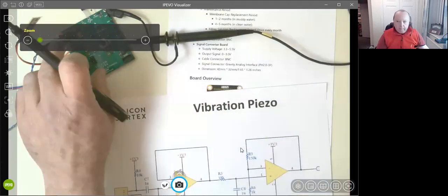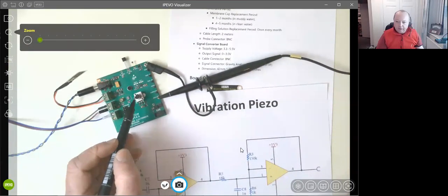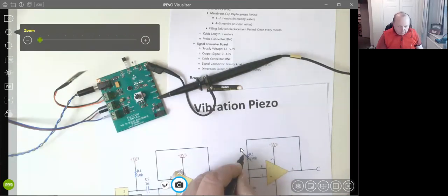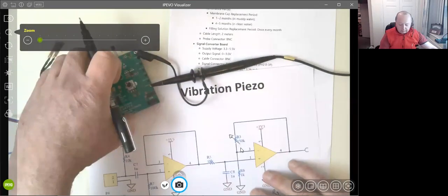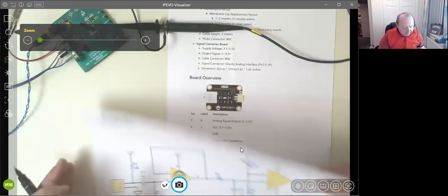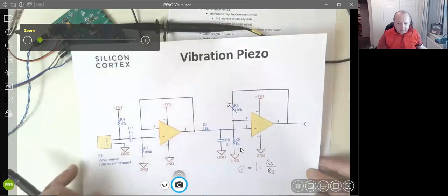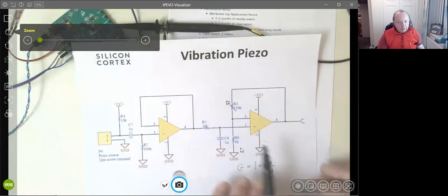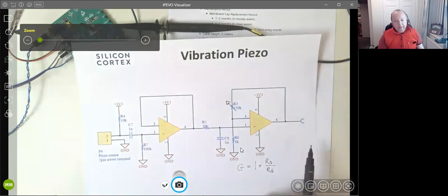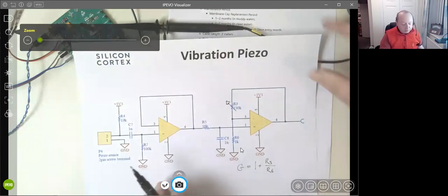So what I've done on my setup here, I could have shown this to you, is this is actually a variable resistor, so I can adjust this 150K in my circuit. There's no one size fits all in terms of the amplification, but I do find generally that an amplifier of sorts, whether a split rail one to get rid of some of the negative voltage, and obviously buffering the input, usually will do the trick.